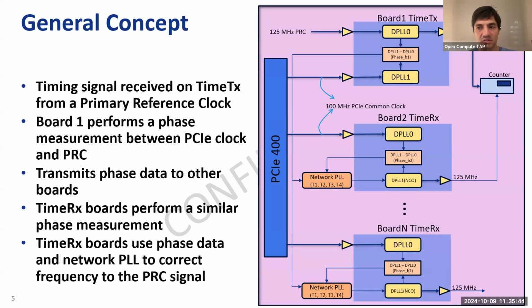Is that correct, Simon? Yep, you would need the PLL with phase measurement capabilities, and you need at least one leader card with the follower cards complementing it, and the 1588 algorithm. And I think that's about it. Well, I guess on the follower card you'd probably want as stable an oscillator as you can afford. But I have not tested the extremes on that, how tolerant the system is to huge offsets on the local oscillators of the other cards.